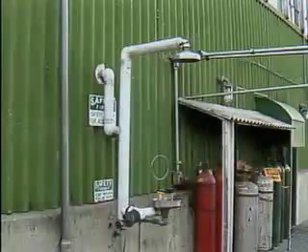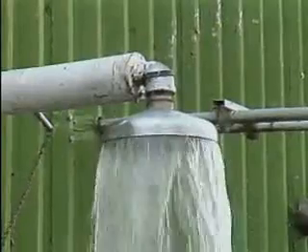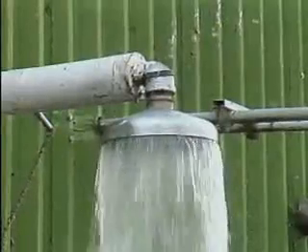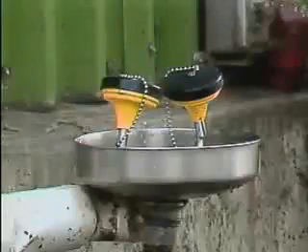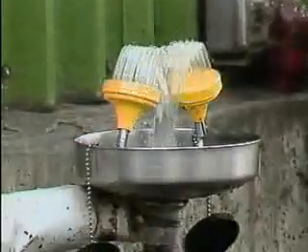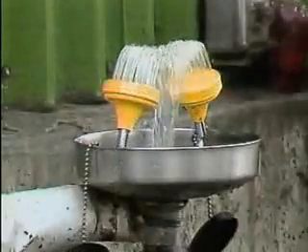If an acid or alkali is splashed on your skin or clothing, or if your eyes are splashed with chemicals, quickly get to the nearest emergency shower and eye wash station. Rinse the affected area for several minutes to make sure that the chemical is completely diluted and washed away. To rinse your eyes, keep them open and directly in the flow of water for 15 minutes.